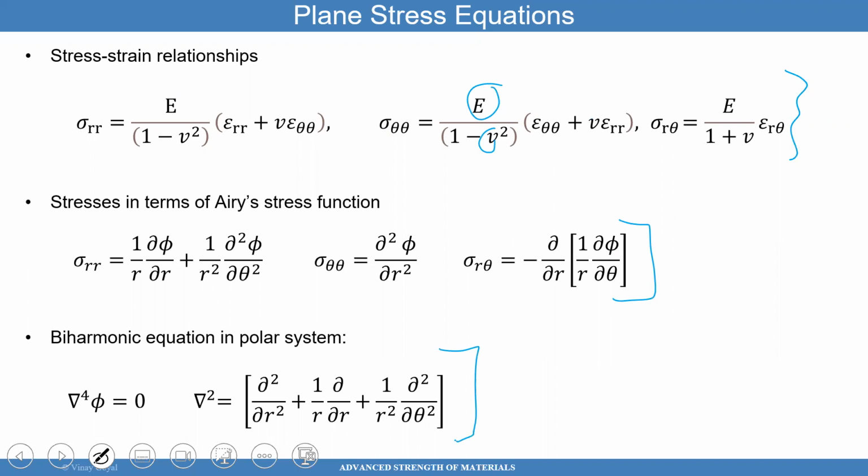So if you recall, the Airy stress function provides a methodology or an approach to solving problems that otherwise may be very challenging to solve. By selecting an appropriate Airy stress function that satisfies the biharmonic equation, you automatically satisfy the equilibrium equations and the compatibility equations. And not only that, you can relate the stresses to the Airy stress function in this manner here. And if you know the stresses, then you can calculate the strains through the constitutive law. And if you know the strains, then you can know what the deflections are, because you can relate the strains to the deflections.